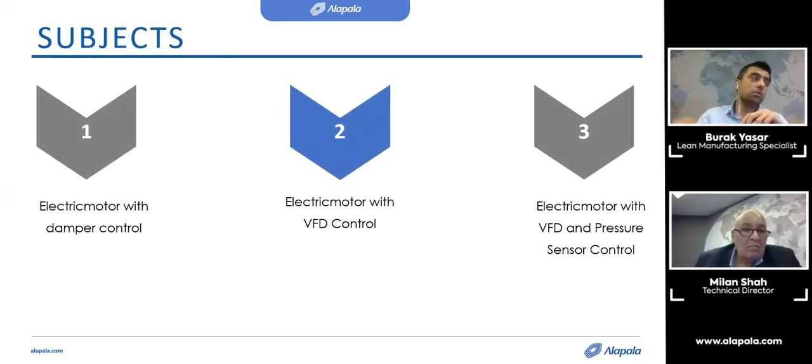Okay. Let's take the constant parameter, dynamic pressure, and guide our VFD based on the hourly temperature and humidity data. There were 3 investigations conducted: 110 Pascal dynamic pressure with the damper control, with VFD control, and with VFD and pressure sensor control. The change in temperature and humidity of the air will affect the dynamic pressure. So this will affect our production capacity, right? And we are still going to consume the electricity.